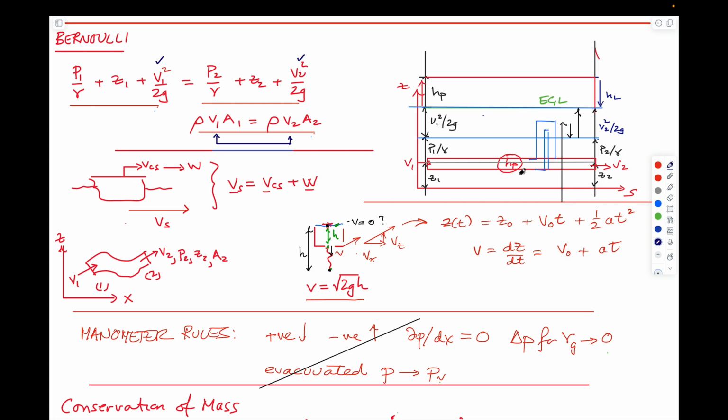They might change. We talked about if you had a pipe that went upwards, then the magnitude of the pressure in this pipe has to change to compensate for the fact that you're elevating the z-coordinate of this point. The velocity, if it's a constant area pipe, has to be the same as it travels through here, so the velocity head has to be the same. And so what gives is that the pressure must be reduced to accommodate that. And so we understand that.